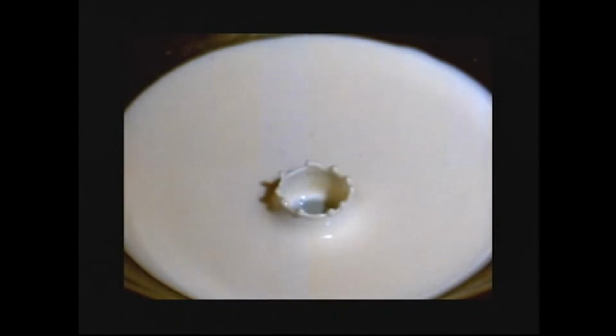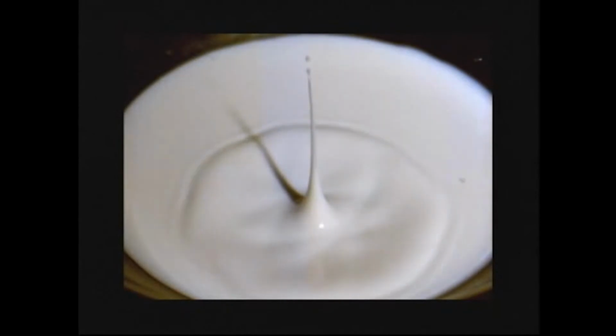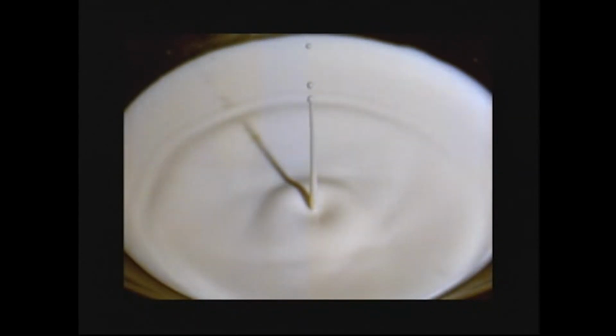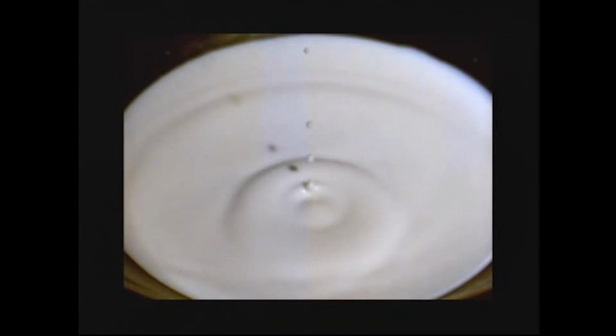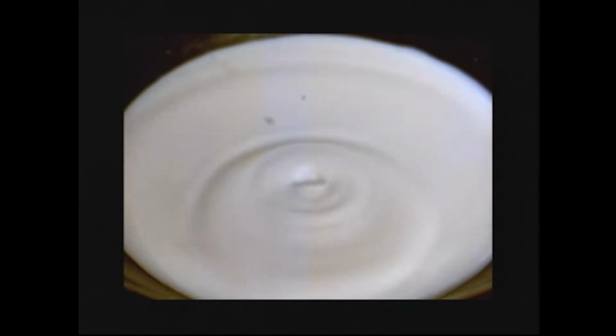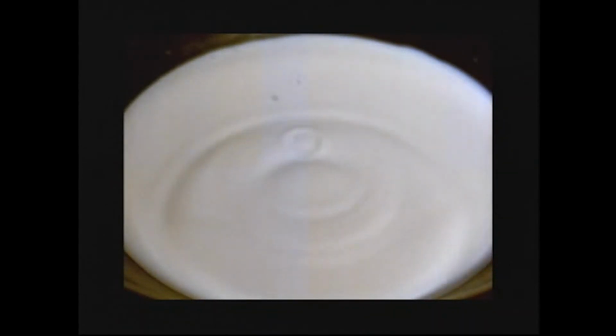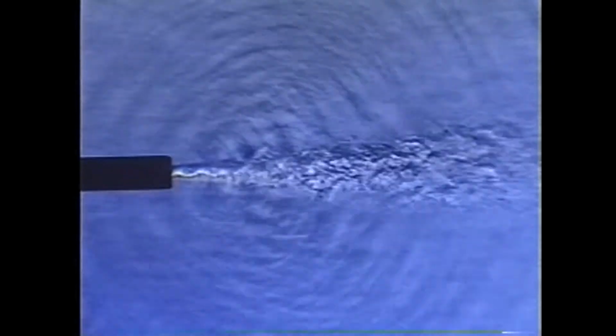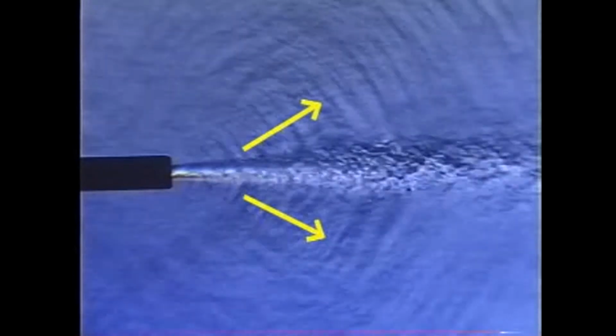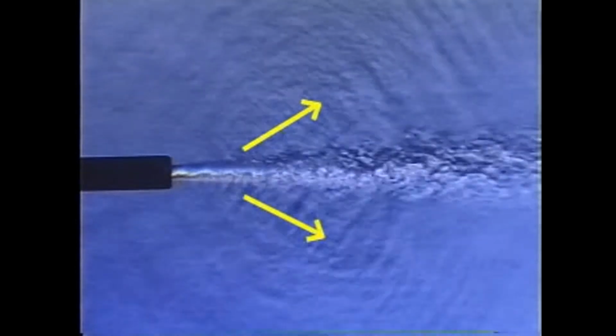Finally, some flows happen too fast to be observed properly by the human eye. High-speed imaging is required to slow these flows down. This milk splash requires no special visualization technique other than slowing it down by a factor of 33 using a high-speed camera. This Schlieren video of a supersonic air jet from a nozzle is shot at the usual rate of 30 frames per second, but each frame is exposed for only 1 microsecond. This is a kind of pseudo-high-speed imaging that reveals the radiation of jet noise from the flow.